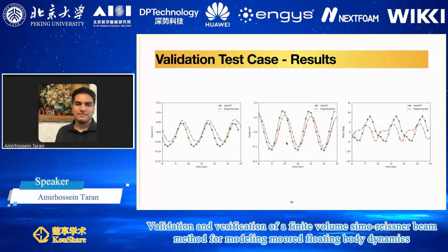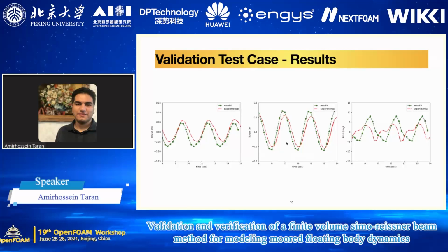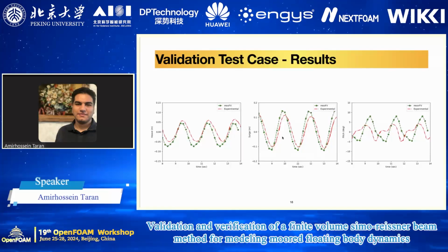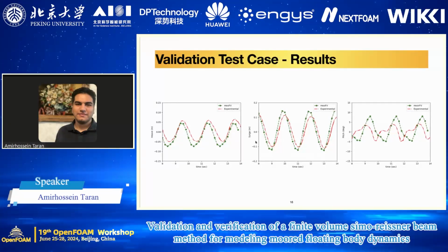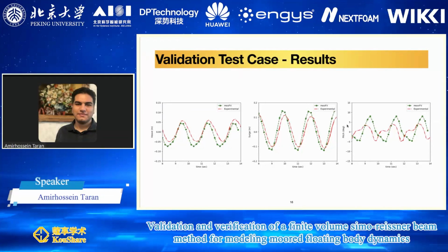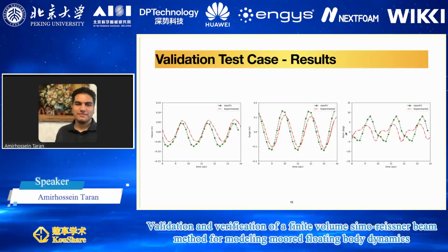The second part of the results that we can get from such a simulation is the box motion. As you can see, with heave and surge, we see an acceptable agreement with our results. The only problem here is in pitch.